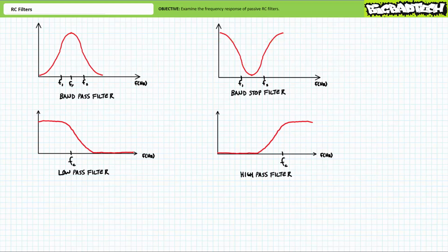Get it? Two other common filters are known as the low pass and the high pass filter. We'll spend the rest of this lecture examining simple low pass and high pass filters. A low pass filter has one operating point, known as the critical frequency, FC. Frequencies below the critical frequency experience greater output. Frequencies above the critical frequency experience less output. As the name implies, a low-pass filter allows low frequencies to pass and rejects or stops high frequencies.